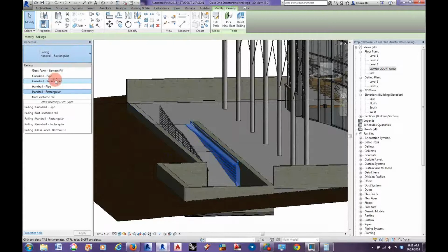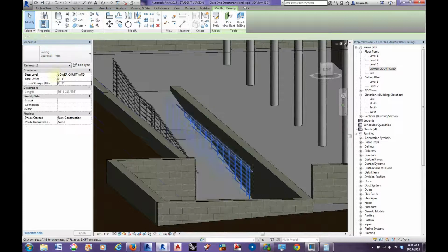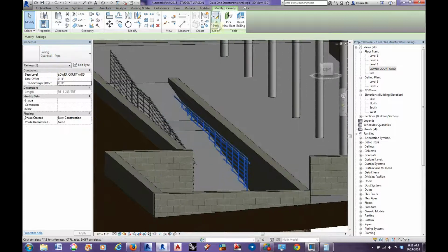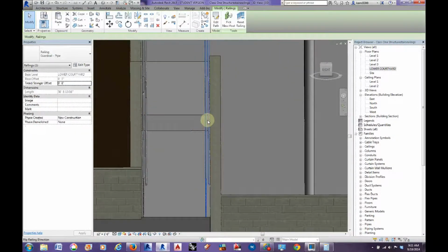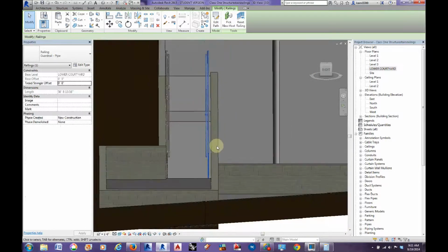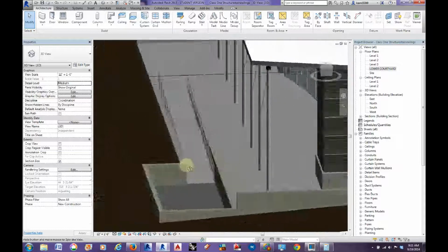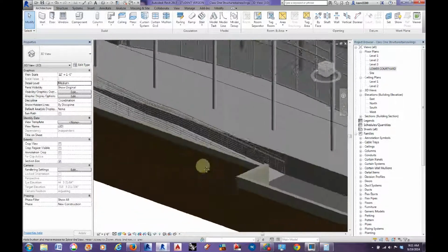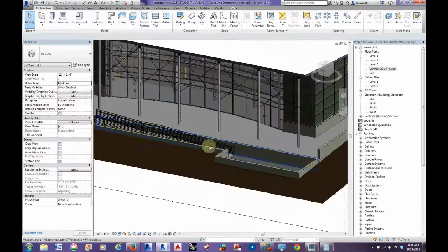Want that type of guardrail. That's my custom one that I never actually changed. There we go. Now that's working more the way we want it to. I'm going to hit that little button to flip the railing to the side that we want it to be on. And there you go. We now have an ADA ramp that goes down to our little lower courtyard space.